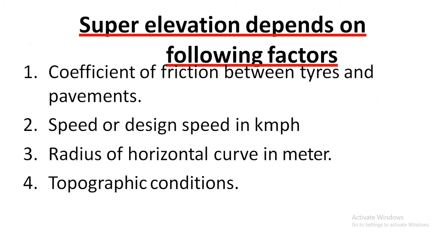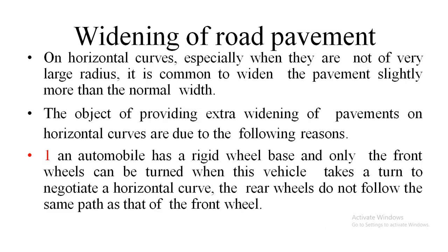Super elevation depends on the following factors: the coefficient of friction between tyres and pavement, speed or design speed in kmph, radius of horizontal curves in meters, and topographical conditions. So that is the super elevation, guys.